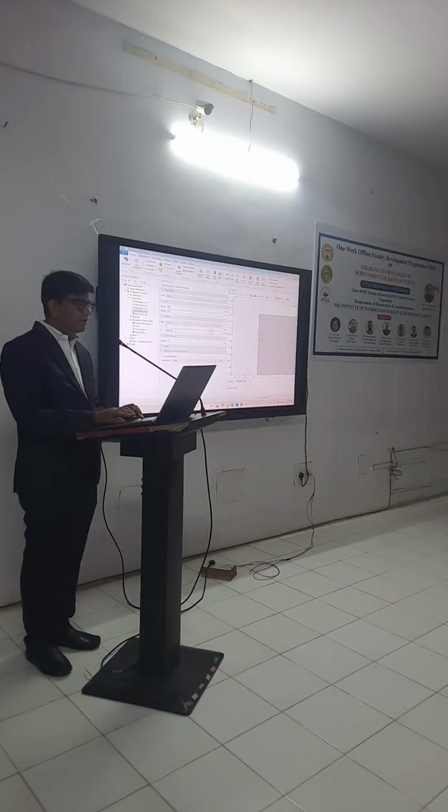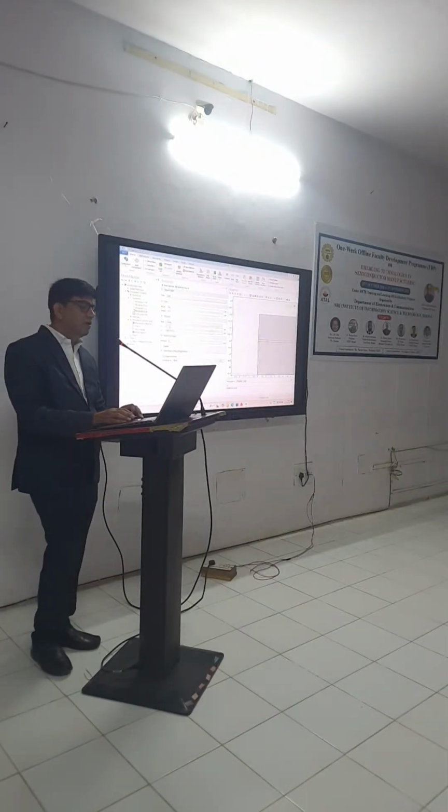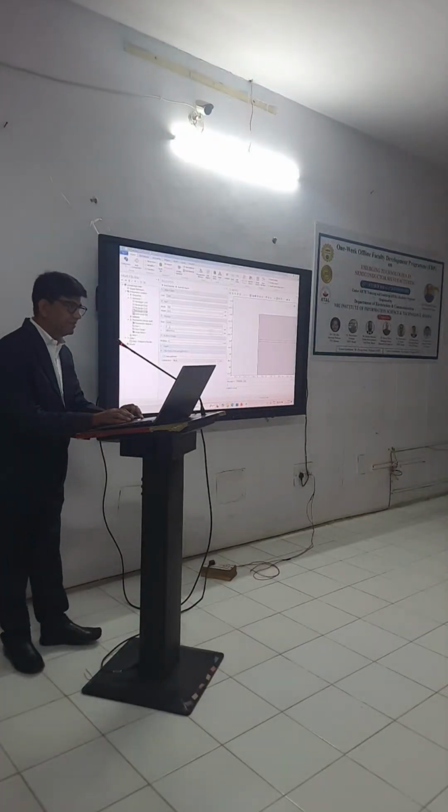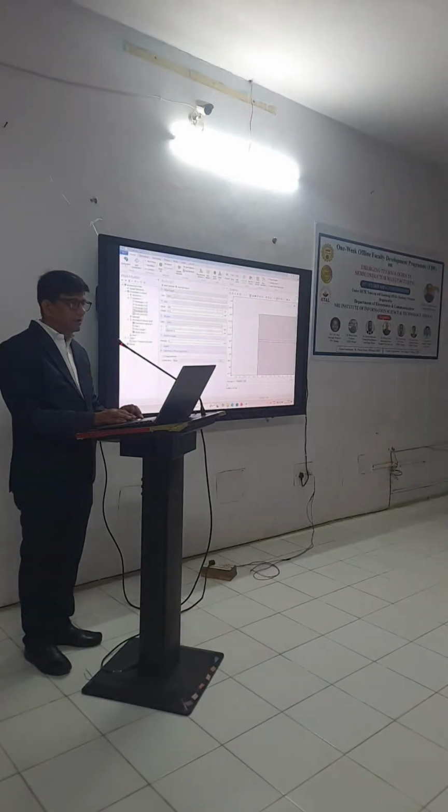Okay. Then what will be the height y? Y is 100 plus 0.15 plus 2 micron, whatever the thickness of your ZnO layer. And then I will see what your x is. Now your x is not 0, because instead of selecting 1000 micrometer width for your top electrode, I selected a width of 750.